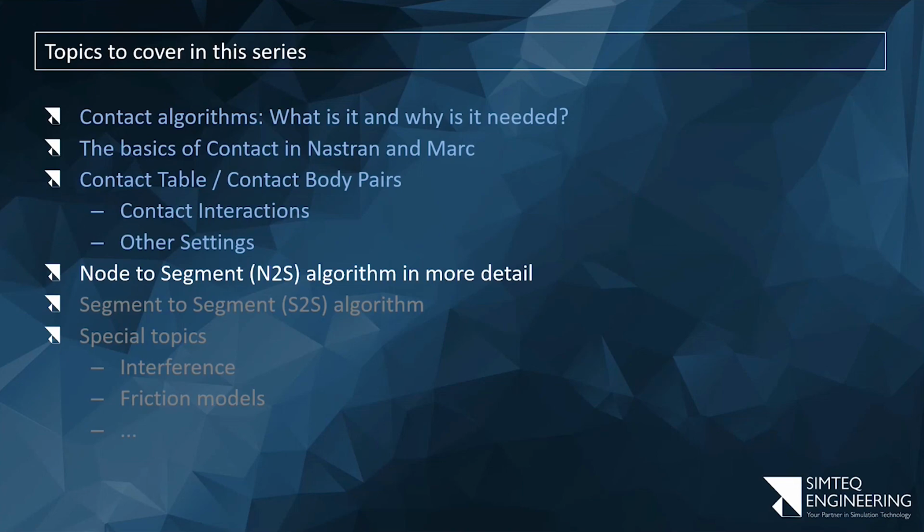The intent of the normal glue is to mesh different parts of the same body differently and glue them together. It's actually one part. It's just convenient to mesh them fine and coarse and even use different elements in different regions. While cohesive is specifically to model something like even simplified bolted connections, but that's a topic that we can spend a lot of time on, but rather something like a glued connection, actual glue, epoxy or whatever. Okay. All right.